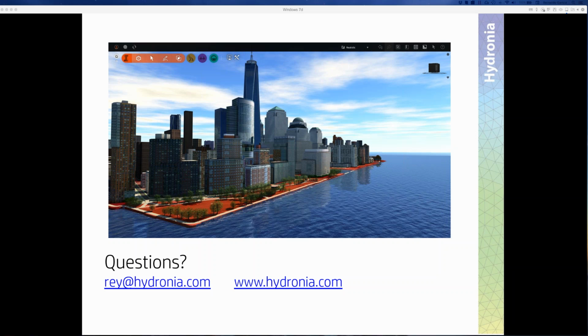Okay, I have a question here that is related to the use of LiDAR data. Any suggestions how to get better flooding results when working with downloaded LiDAR data that does not contain surface data below the waterline? Yeah, that's a big issue because as you know, the LiDAR data ignores what's below the water surface. And when you're solving a riverine problem with LiDAR data, that data assumes that the water surface is flat.